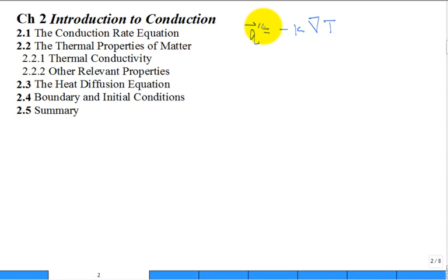Could we write that and express it in rectangular? Yes. Cylindrical? Yes. Spherical coordinates? Yes. All three dimensions in the spherical and cylindrical? Yes, although we almost always just use the radial in the cylindrical and the radial in the spherical. Very simple. Don't get bogged down with those thetas and phis. They can bog you down, but most of the heat transfer problems in cylindrical and spherical are radial.